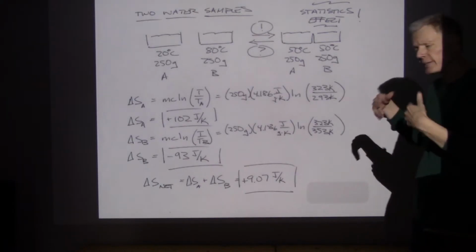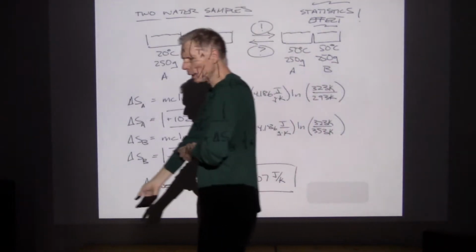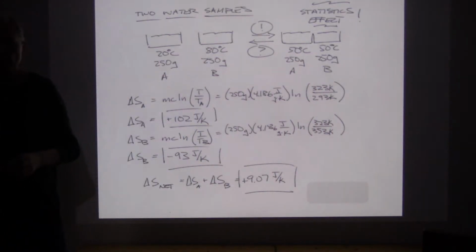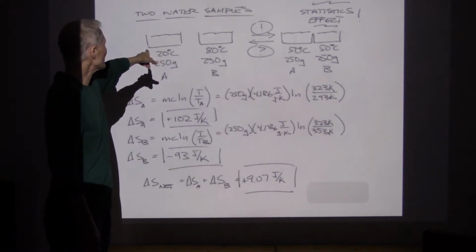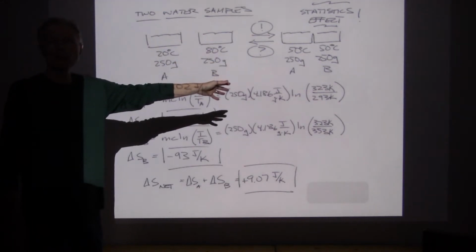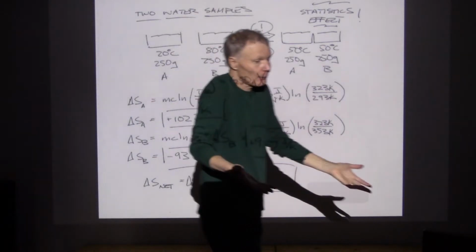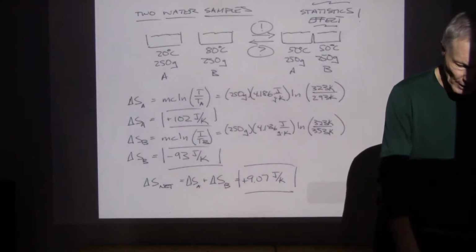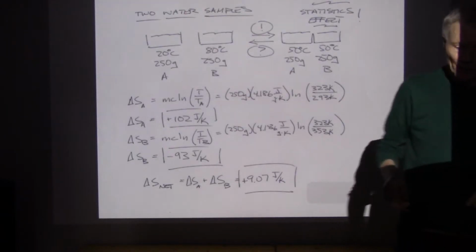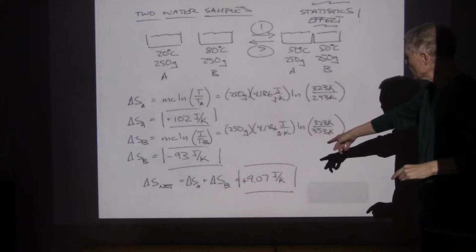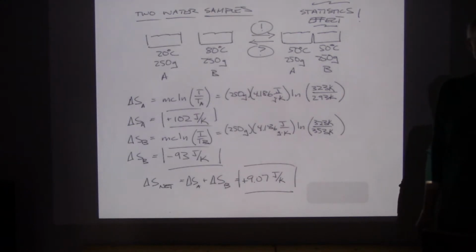So the second law is statistically driven. You can actually calculate the likelihood that these two containers would spontaneously unmix, and it's not going to happen. So this is the calculation of entropy, and anytime we see the entropy go up, it's an indication that it's not a reversible process. It will not reverse, at least not on its own.